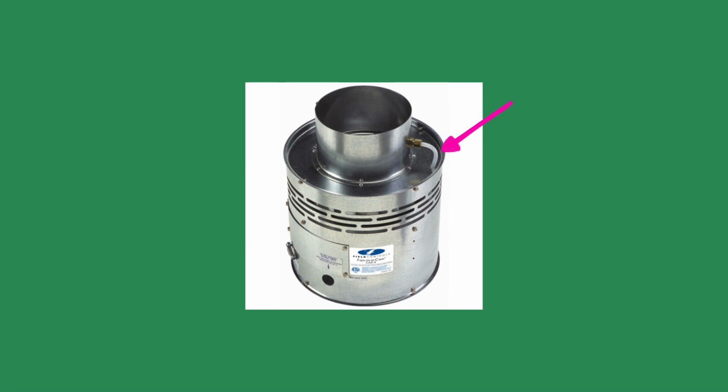The operation of the fan must be proven before the burner starts so it does not starve the burner for air. Most fans use a differential pressure switch to verify fan operation. Some combustion air fans, like the one from Fields, have an integral switch. We have had success with these fans.